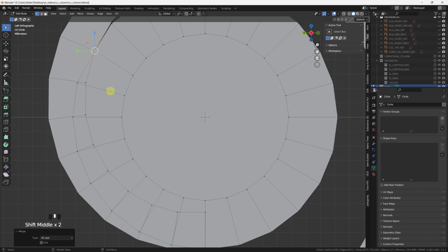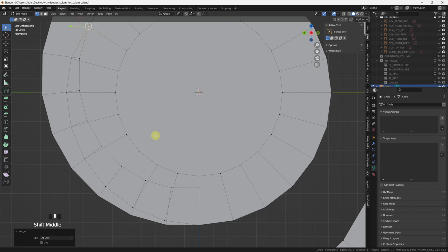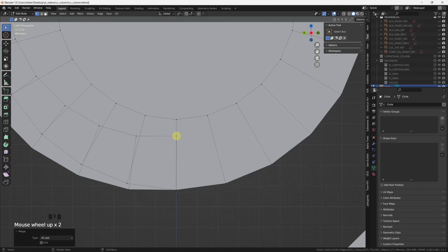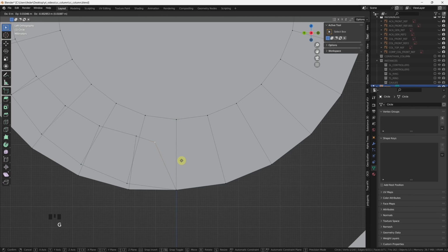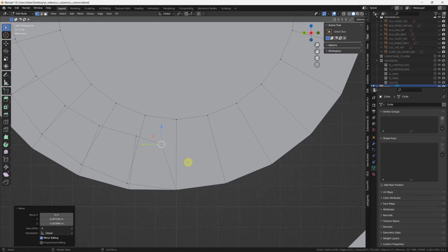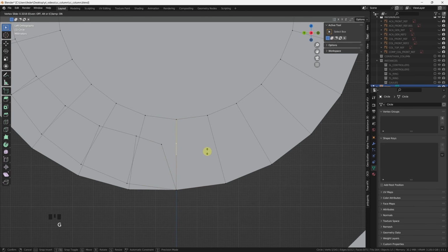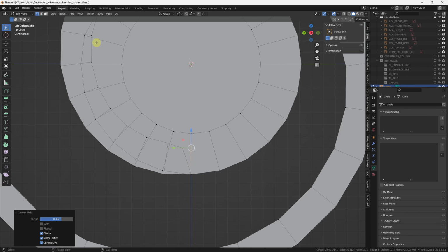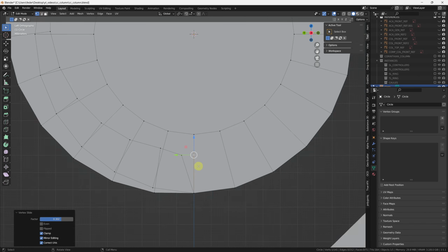For the rest of the geometry, I want this line to survive and to eventually collapse right into this big circle. And to do so, I'm going to operate in this way. So we have some floating vertices. I'm going to select this section here, subdivide, take the resulting vertex, and I'm going to double press G to slide it into position, where its position is this ideal line right here.